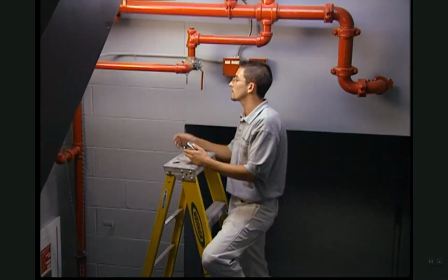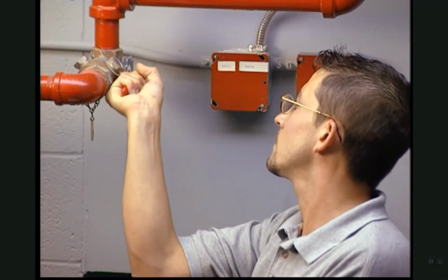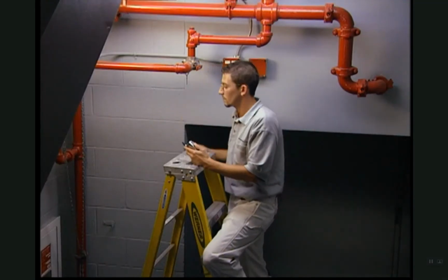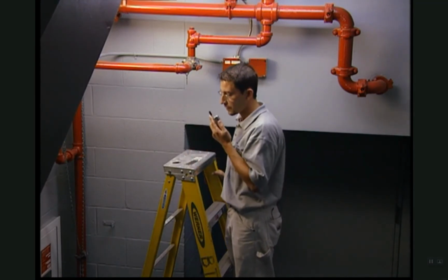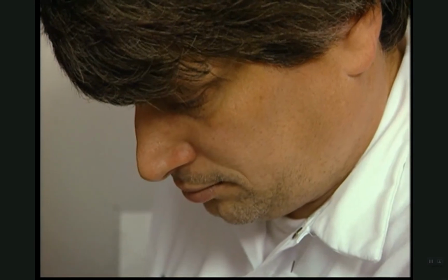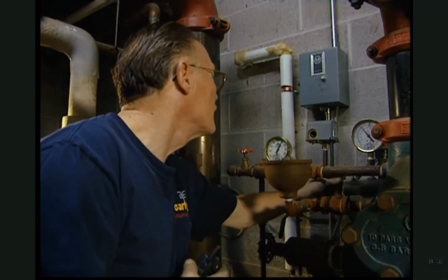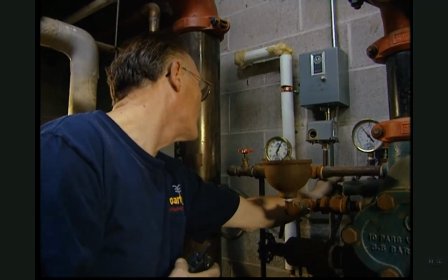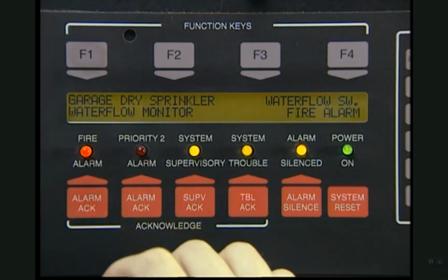Make sure the water flows long enough to activate the switches in all parts of the affected system, such as a standpipe, main flow pipe, or fire pump. Record the time it takes for each switch to activate. If the signal doesn't transmit within 90 seconds, adjustments are needed. With a dry pipe system, flow water through the alarm test bypass connection and verify receipt of alarm.